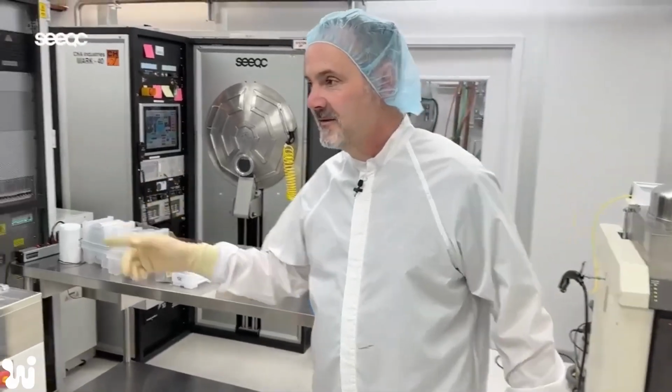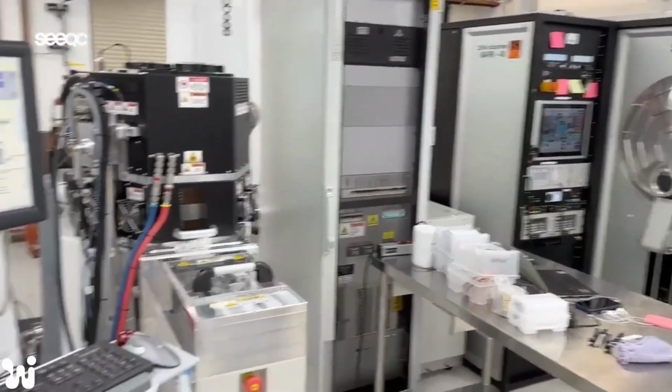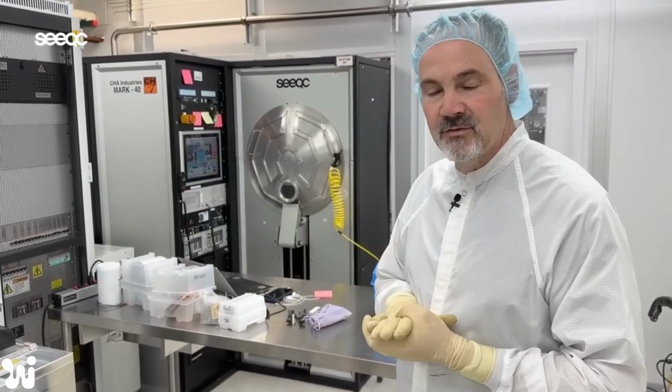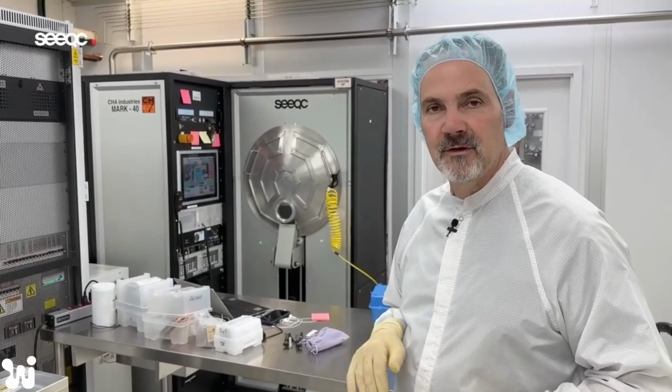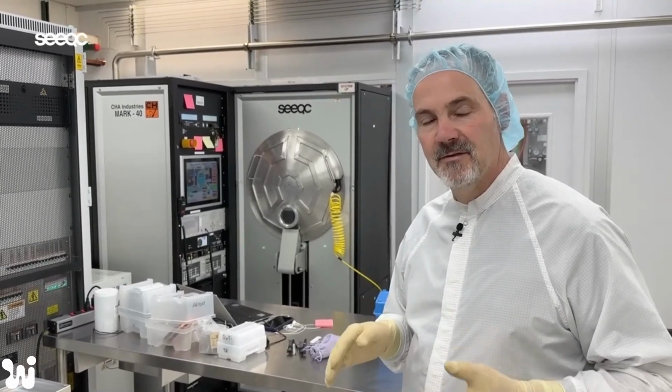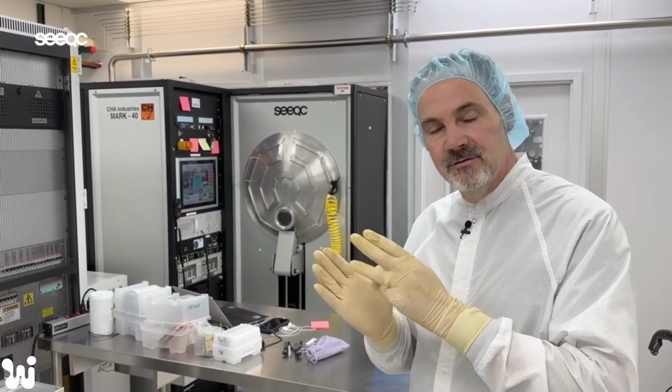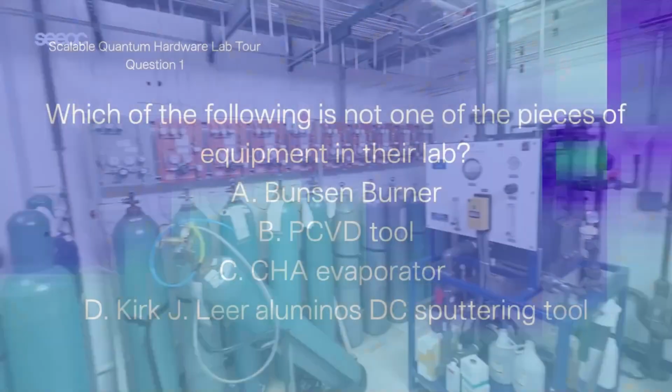This is the latest addition to the fab. It's a deep silicon etcher. Basically, we use it to etch vias through the silicon so we can access the back side of the wafer. We're hoping at some point in time to have metrology and circuits on both sides of the wafer.